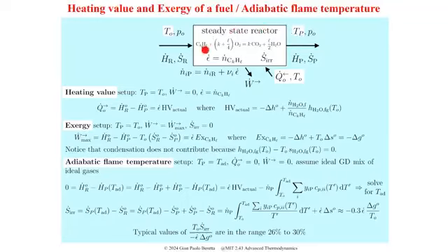But your reactor has some system inside that allows you to extract work and actually does it reversibly. In order to obtain the maximum work, you set the entropy produced by irreversibility equal to 0 in your entropy balance, and the outcome is this one. And the exergy of the fuel turns out to be equal to the negative of the Gibbs free energy at STP.